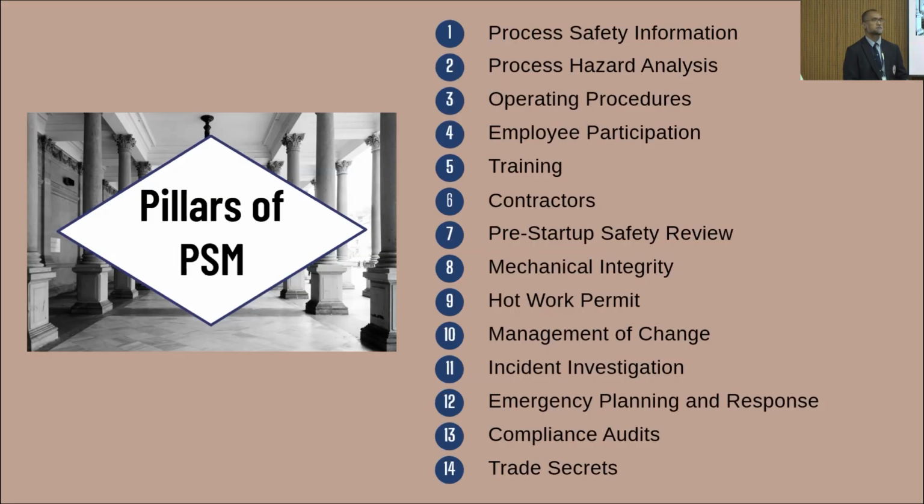Hot work permit, if you're familiar with it, that's fine. Management of change. If you look into the industry, most of our accidents end up when people change things, but they don't change it systematically. Records are not available. The next shift doesn't know what the previous shift did, so we need to manage your changes. Unfortunately, things happen. So when things happen, we need to investigate why.